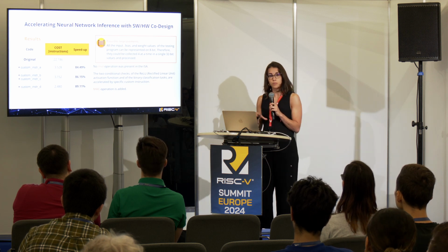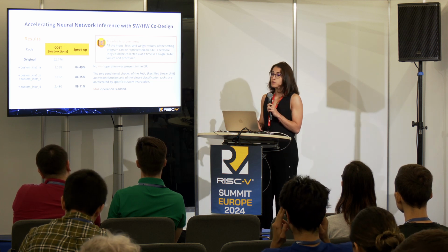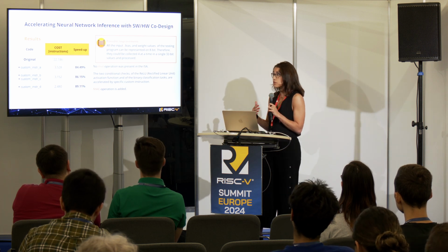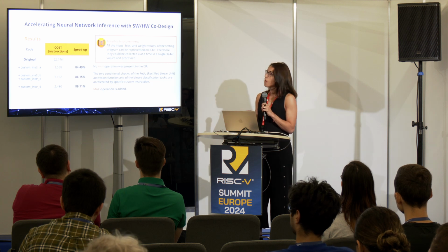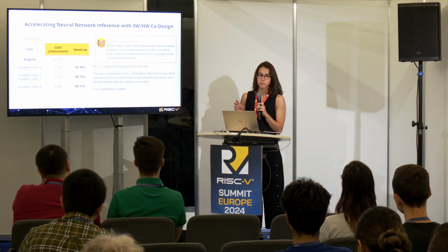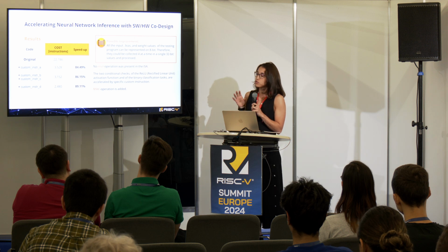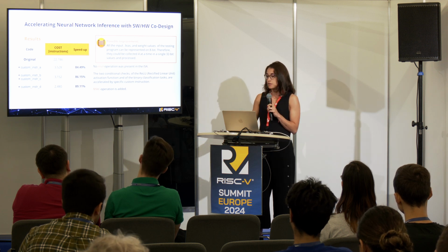considering the length of the inputs, is that the inputs, the weights, and the bias can all be represented on just 8 bits. So one possibility was to combine each of these values and perform a vectorization of the operation, therefore performing multiple multiplications at a time. I didn't have the time to look at it, but of course it would be a more specific implementation, because if we want to keep the flexibility of the solution, we need to consider that the input should be 32-bit. So this could be a possible improvement just for the specific application that we were given.